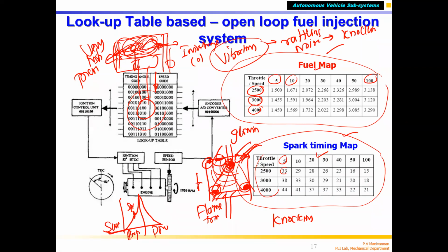Without giving a spark, the combustion in the SI engine can happen because of carbon deposits. That's why you have to regularly remove the carbon particles inside your combustion chamber. This is called decarbonation, as a mechanic will say. This is called unwanted combustion.